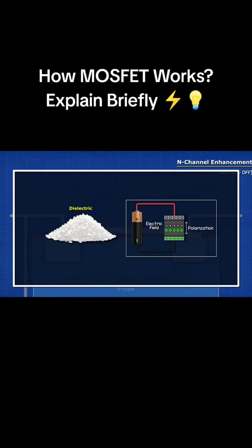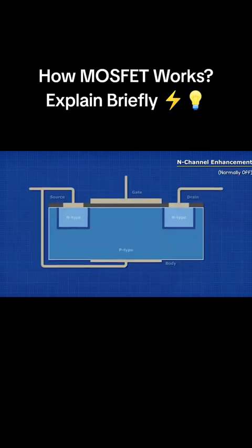It is also a dielectric material, so if we apply a positive charge on one side, a negative charge builds on the opposite side, and an electric field forms between them, just like a capacitor. So we have metal oxide, semiconductor, and a voltage on the gate pin creates an electric field which affects the material of the transistor. Hence, we have MOSFET.